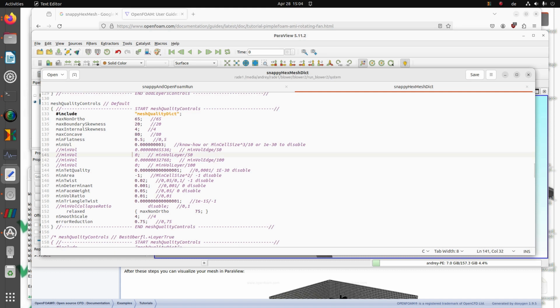So why is the minimum volume so important? The simplest reason is that it can be critical for transient simulations due to the Courant number. A mesh refined in the wrong places can lead to problematic or non-physical results. So in this mesh I set the minVol in two different ways. One way is the minVol taken from experience, like it was done here, know-how.